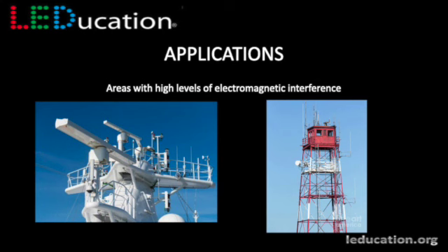Areas with high levels of electromagnetic interference. Anybody ever tried to run a Bluetooth device at Light Fair? Last year we had a robot that does UV disinfecting, and it works on a Bluetooth wireless controller. We literally were standing 5 feet away from the robot, and it would not respond. Or when it did respond, it did exactly what we told it not to do. And that's because the saturation of wireless signals in that room during Light Fair is insane. So, just not a good environment for Bluetooth. Well, where else does that happen? On a ship, the conning tower right there, it's just being bathed in radar and every other type of horrific wireless thing.